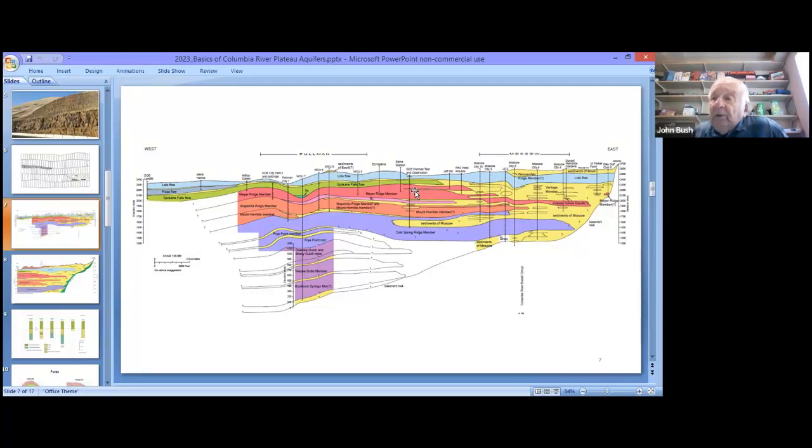When you look at those well logs in the lower aquifer, you'll find out, depending on how the driller described them, but if you look at most logs, you can see, wow, there are good, well-developed intraflow zones. If you look at a nearby well without the basalt chemistry, you can say, wow, same elevation 3 miles away, same intraflow zone. So the central part is well interconnected in intraflow zones.